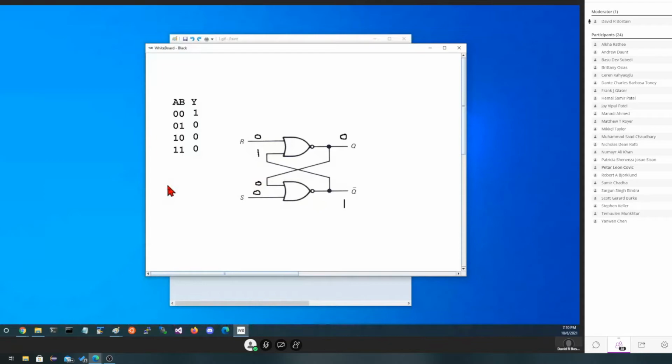What I'm going to do is build another truth table over here. S and R and Q. So 0, 0, 0, 1, 1, 0, and 1, 1 are our possible inputs. Okay, so we said just now 0, 0, we think either produces a reset state or it produces a don't change state.